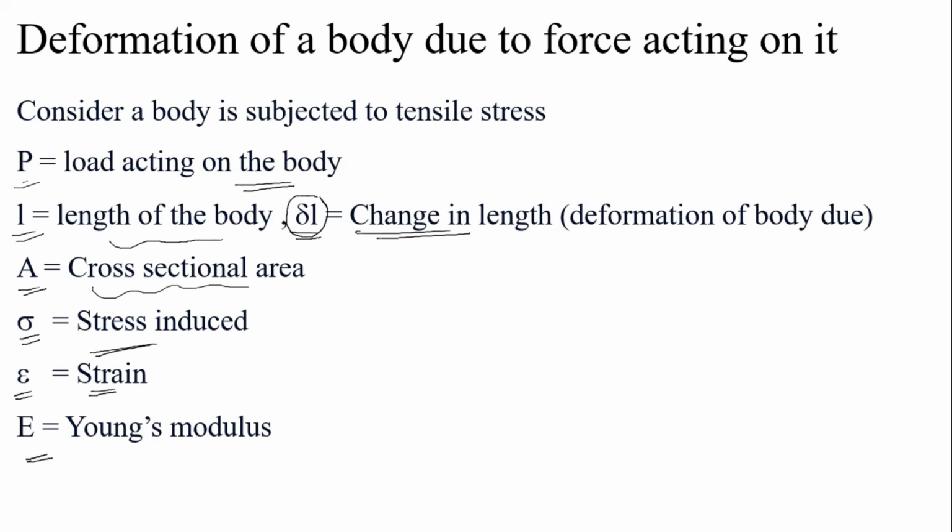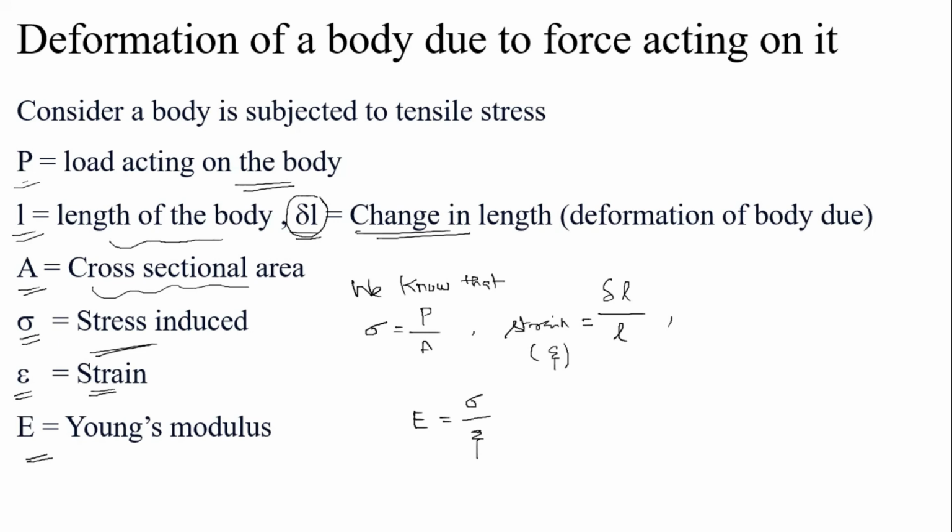We know that stress is equal to load by area. This is one formula we already discussed. Now strain, epsilon, is equal to del L divided by L, change in length divided by original length. Now E is equal to stress by strain. Now substitute the value of strain.